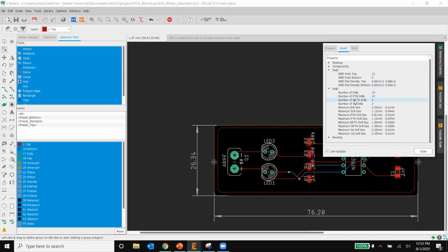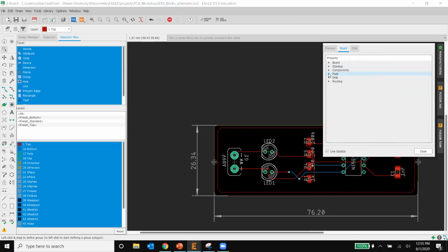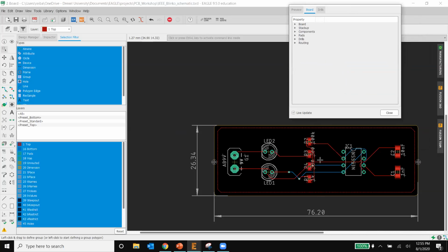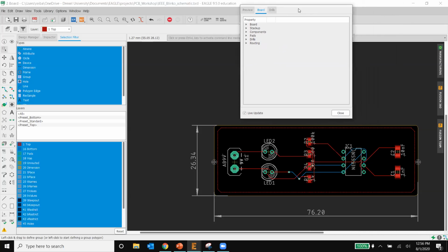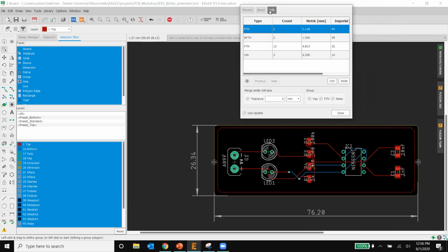These are very important things to take care of, because if you think about it, and if you're producing something on a very large scale, and for example you're putting a printed circuit board in a car, you have to check the stresses, you have to check the thermal heats and everything, and all these components, these through holes, the way they're put, the way the stress is distributed in this board, everything is very important. So the more complicated your job is, the more things you have to look at. And these are the drills that are used.